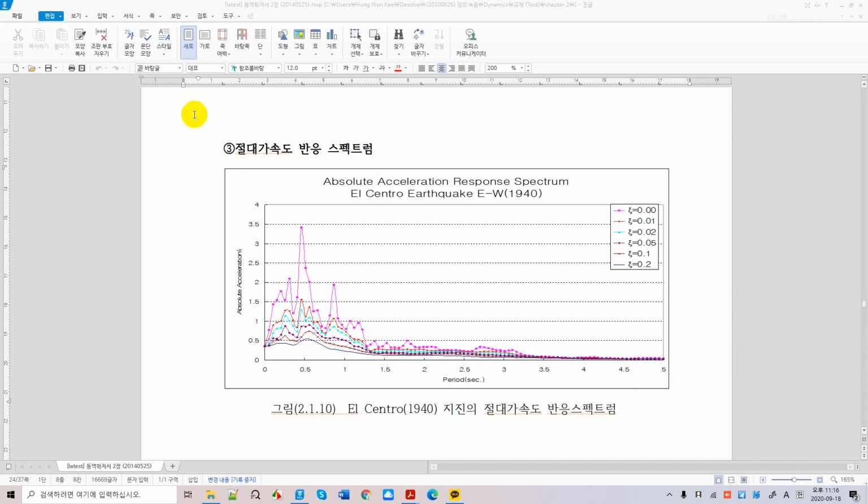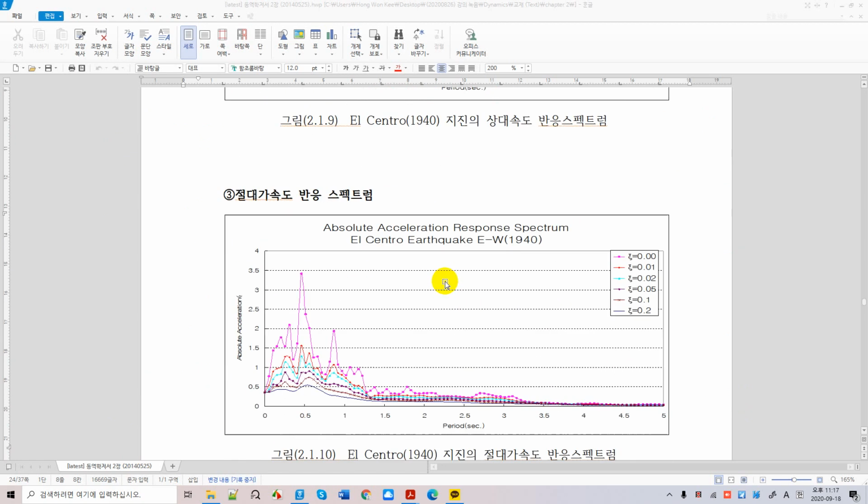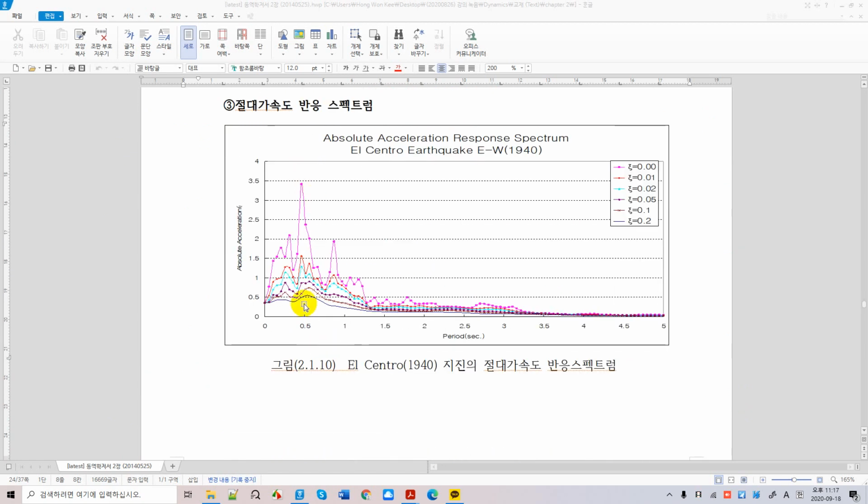All the engineers, in the United States, England, Japan, Korea, use the same response spectra. So you don't want to forget that if you want to work on high-rise buildings and seismic design. These seismic designs are pretty easy to understand, but you probably don't want to forget this. And the resonance area is at 0.5 seconds, so you're on very stiff soil.